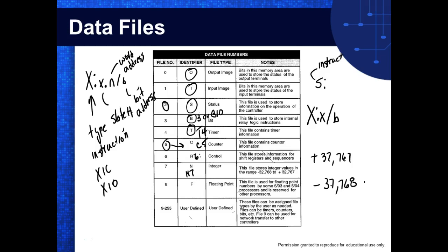Because if you go past 32,767, what would be the next count? A -1. So the counter would flip over to a -1. So we've got to understand that, right? So we can monitor that and see when it happens. So the overflow flag goes on as soon as it converts to negative.